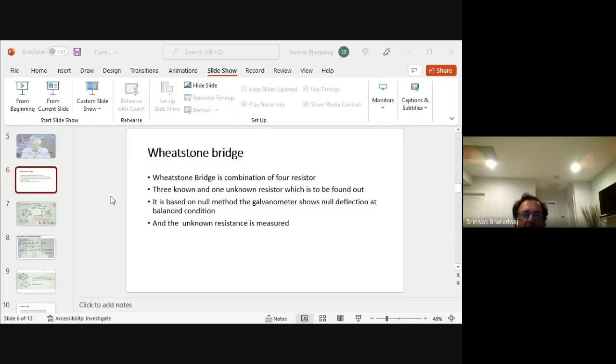Okay, this part and this part and this length is balanced, and as a result, you can then say that the potential gradient for null deflection, the gradient given by this, is equal to phi times L1. When the potential gradient between these 2 points is E equals phi times L1, then there is no current through the galvanometer. That happens when it completely cancels out.